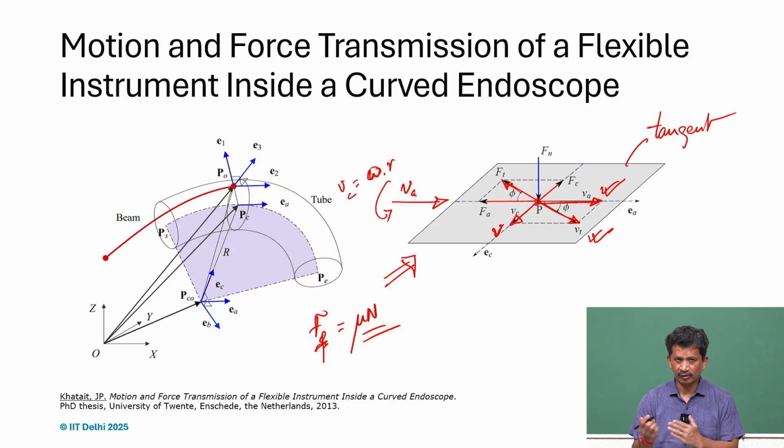And what we realized is that there is an angle between the axial direction and the actual friction force, and this angle is defined by phi. Ultimately the force along the axial direction is only the component in that direction. From the figure itself, you can see that it has reduced, and is simply the cosine component of Ft.